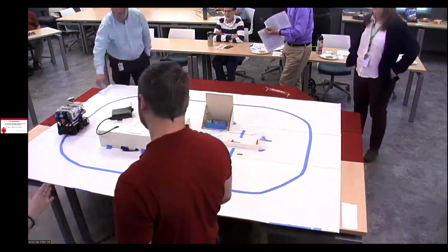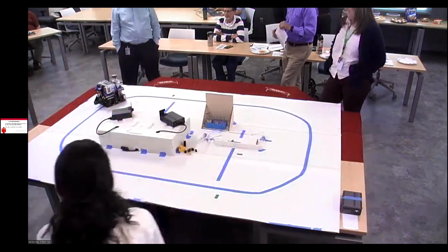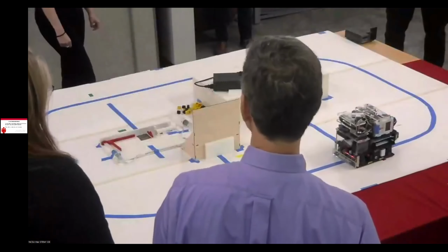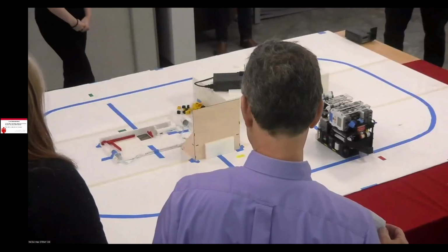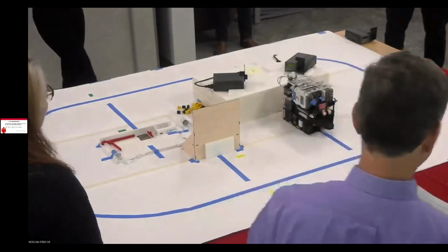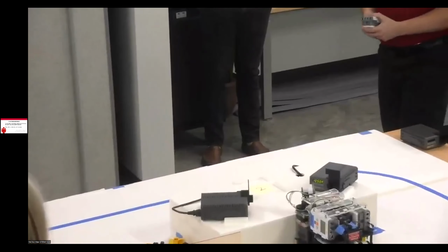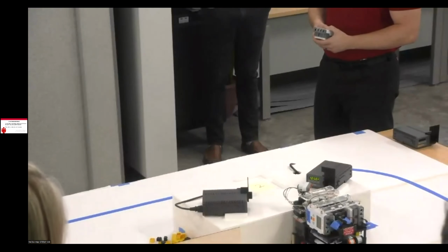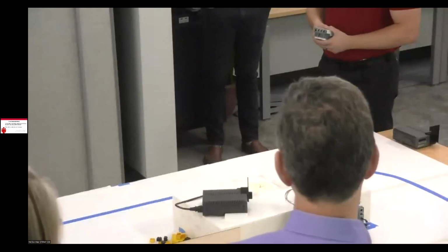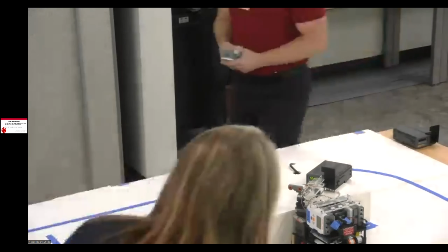There's pauses for Bluetooth and stuff. I tried to use my hand one time, my hand's too small. It does not like to roll over the dowel rod. So the issues that we found is that for the length of the time that we were given, the 2-inch line, with our center drive wheels, when it pops over, it does not register. It thinks it's lost because the line moves itself.